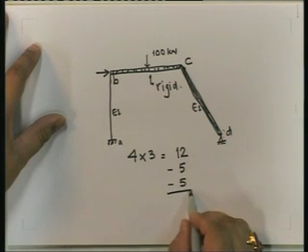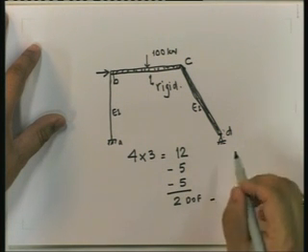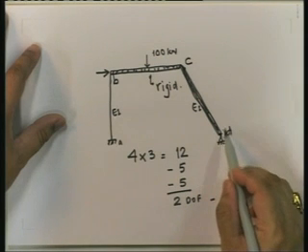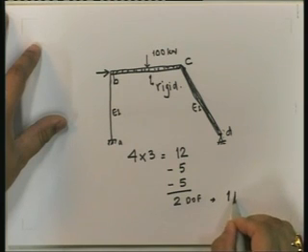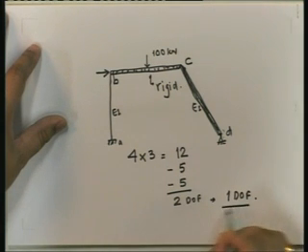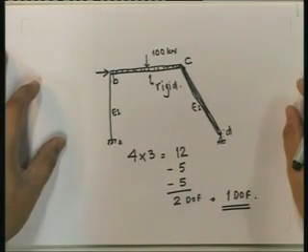So that means there are 2 degrees of freedom. Okay, but one of them happens to be this end rotation, where anyway we know the moment is there. So I have only 1 degree of freedom, essential degree of freedom. There is a second degree of freedom here, which I don't want to find out the displacement right now. Okay, so this goes as a single degree of freedom system.